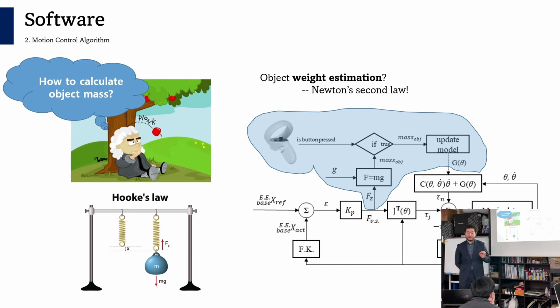If I could determine object's weight, then I can update manipulator's model accordingly, so manipulator would act weightless. In order to calculate object's weight, I utilized one of the most fundamental laws of physics, aka Hooke's law and Newton's law. Hooke's law provides us a formula to calculate force, which is applied to carry the object by using spring constant and displacement.